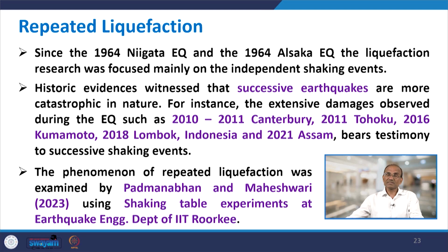What has been observed is that since the 1964 Niigata earthquake and 1964 Alaska earthquake, liquefaction studies focused primarily on independent shaking events, which we have discussed earlier also. A lot of liquefaction studies have been done, but most of them are on independent shaking events. That means the shaking has come and you assume it is a kind of fresh shaking. The soil is subjected to some shaking, but we do not account for the prior history.